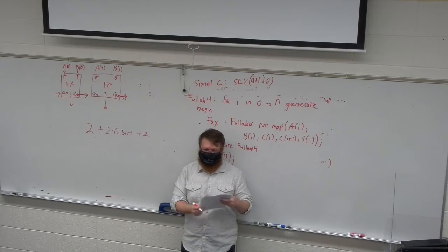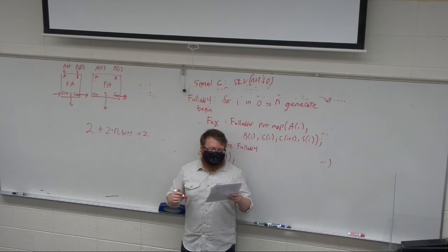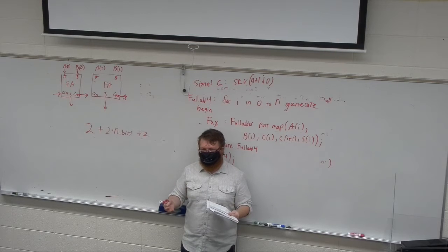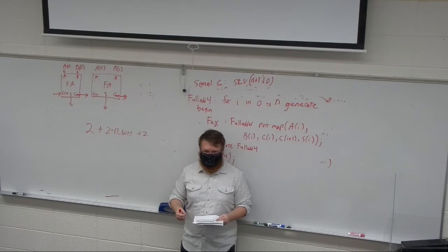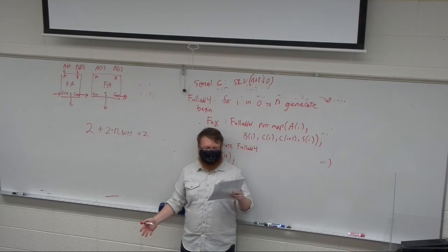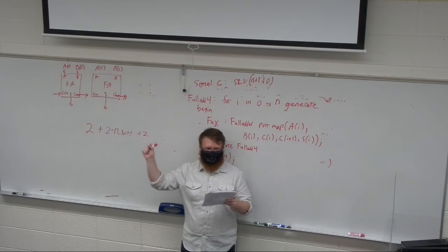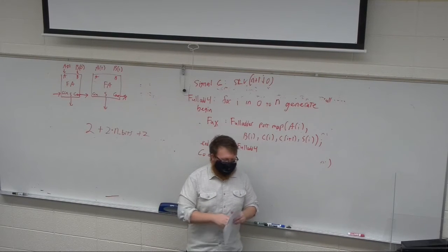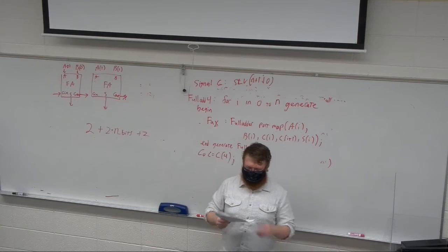I actually don't know what logic they use to generate their 8. As far as the fast carry, again, I don't know what they use. It's not that hard to make a 4-bit with only 4 gate delays. In fact, the most straightforward implementation is 4 gate delays. But the table says 5 or 6, I think. So for 8 and 9, tons of people, not everybody, some people actually figured out the circuit of the adder, like, okay, that's 12. But I can't blame you guys because the book said something else.